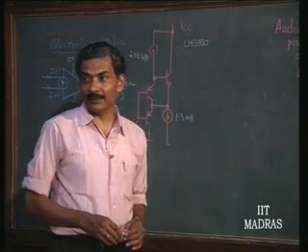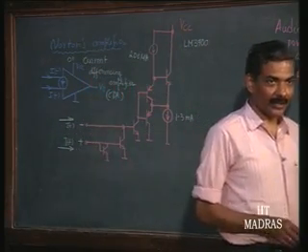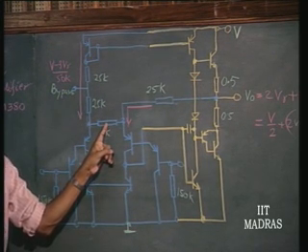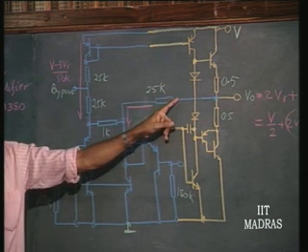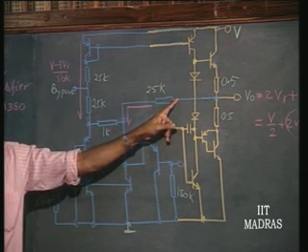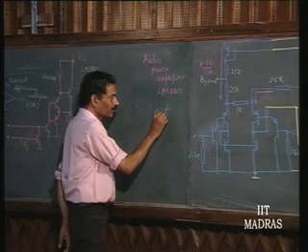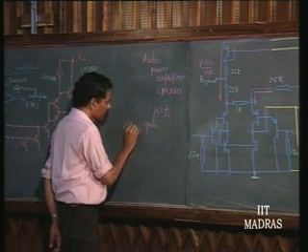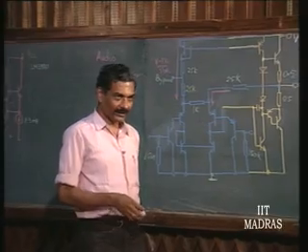That is as far as the operating point is concerned. As far as the negative feedback for the signal is concerned, once again we will adopt the same strategy that we have earlier adopted. For signal operation, we can consider that the midpoint of this can be grounded. That means, what is the feedback factor? The 500 ohms and 25K is the feedback factor, which is going to give a gain of, because beta of 1 over 50, a voltage gain of 50, assuming that the open loop gain is very high.